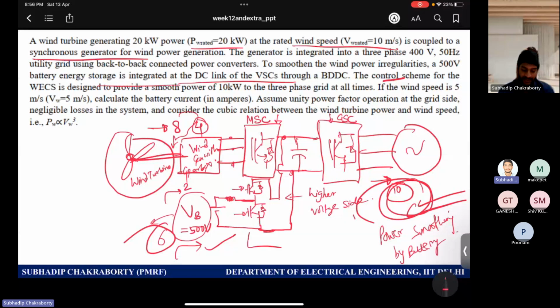But how are you controlling the battery? Using a bidirectional DC-DC converter. So these converters are quite common and are mostly used with battery control to control the battery, right? Otherwise, directly interfacing the battery, you don't have any control over the battery current. So if you have some converter which can regulate the battery current, you have control over the battery current, right? So to gain control over the battery, we need to interface it not directly, but using a DC-DC converter, which is termed as BDDC. Okay.